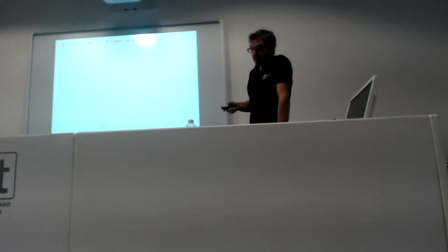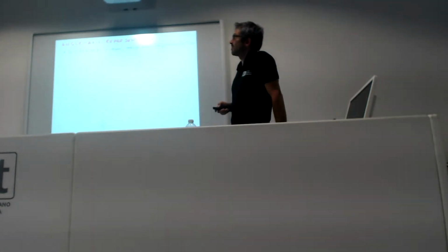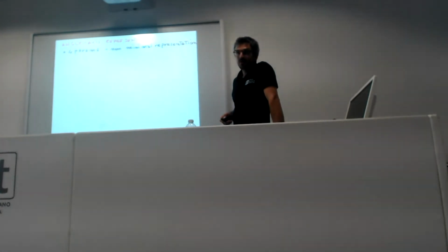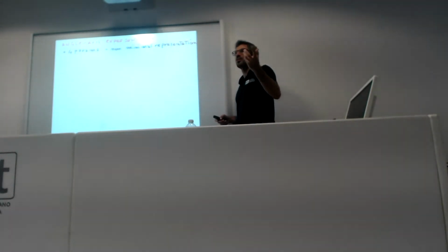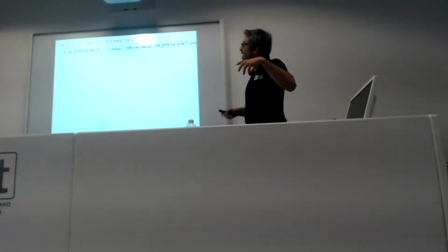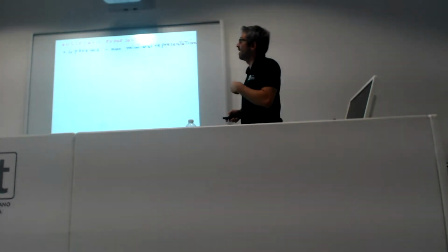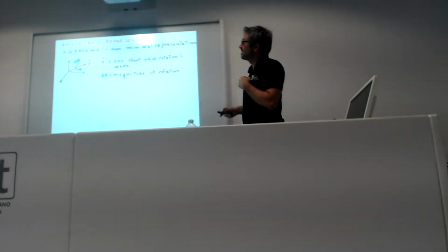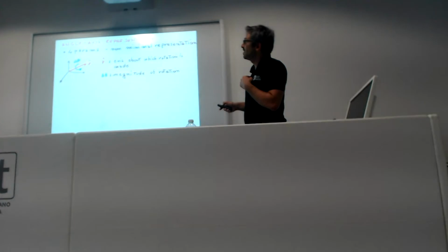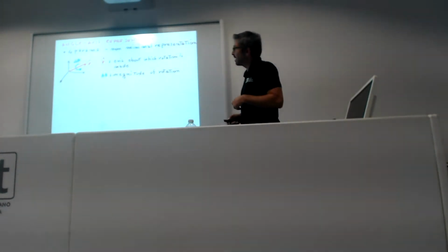The first one we'll talk about is the angle axis representation. It involves 4 parameters. For this reason, it's a non-minimal representation, because the orientation has 3 degrees of freedom, and we represent this with 4 numbers. The angle axis is as follows. You have an axis element and a scalar element, and the axis element is a unit vector that is the axis about which the rotation is made.